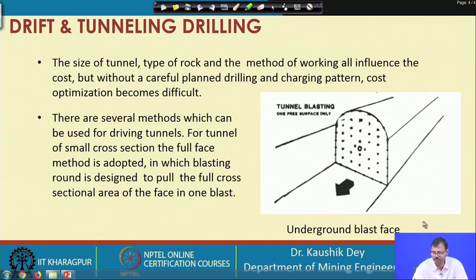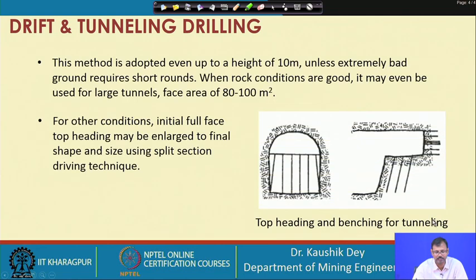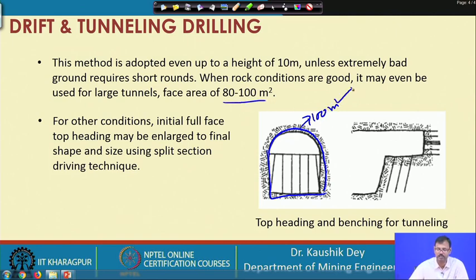So basically the purpose of underground drilling is that it has to be carried out initially in such a way that another free face is created. Often, if the dimensions are very large, say 80 to 100 square meters, then only the top portion is excavated in the similar fashion carried out in underground drifts or tunnels, and the rest of the part is carried out with a surface excavation technique.